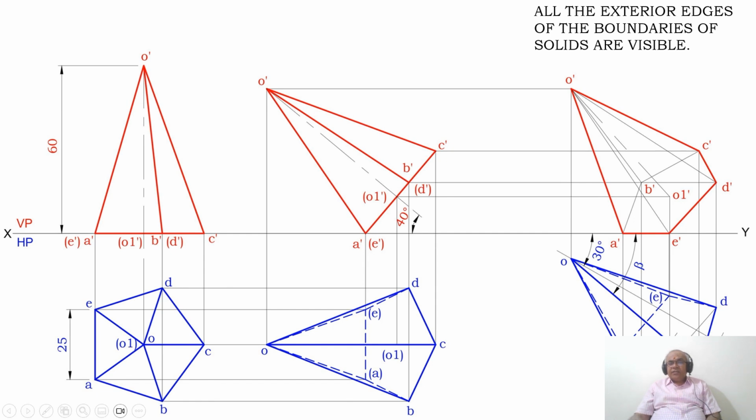Once you do that, then using the scale with reference to this, you draw a horizontal line that is going to become the locus of O1. As we know, this is the apparent length. So, using the compass with O as center, take the radius of O1, and with the same center O cut an arc on the locus line, and you mark that point as O1 in bracket.